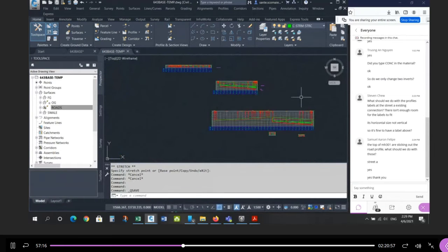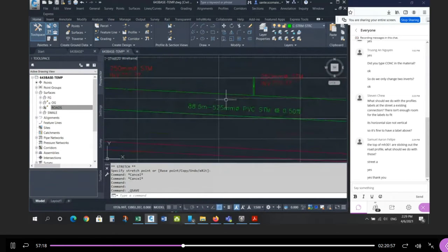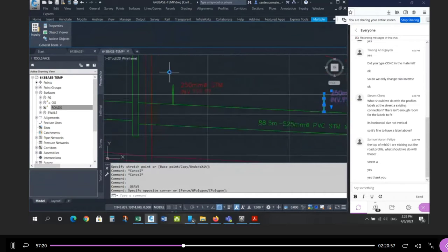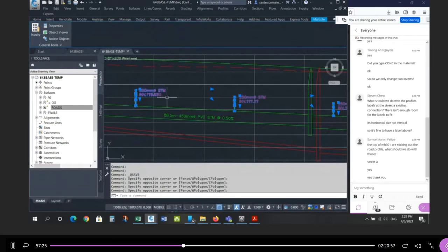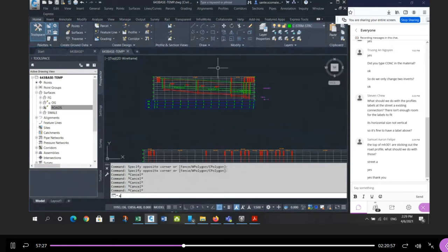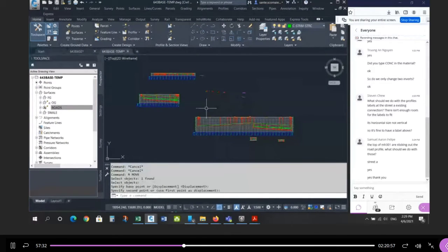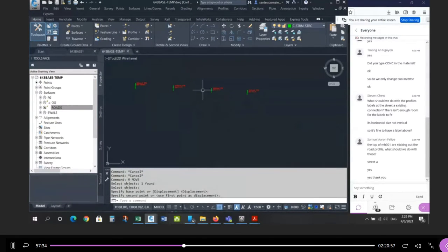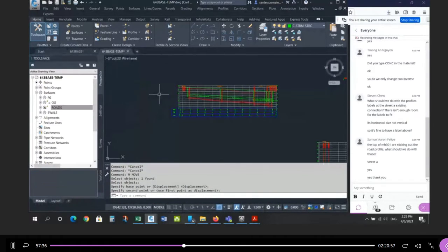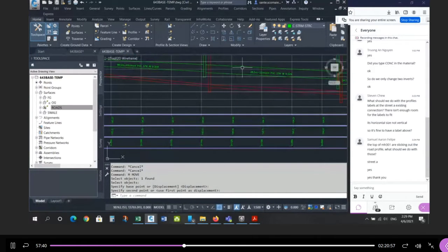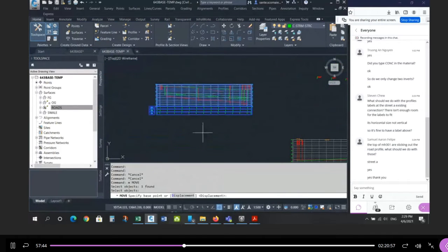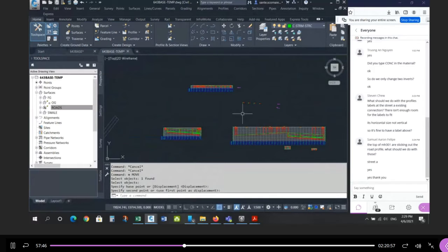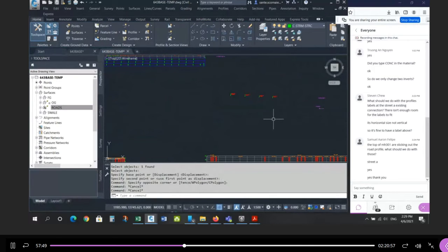All right. So when you draw this information, this is all AutoCAD, right? You need these rear lot catch basin information. This stuff, this is all AutoCAD. Watch what happens. If I move the grid, the profile view, that stuff doesn't go anywhere. I drew it there. It's not connected to the database. These pipes are drafted in this profile view. So when I move the view, anything drafted by Civil 3D goes with it. Anything that you drew in AutoCAD is static.